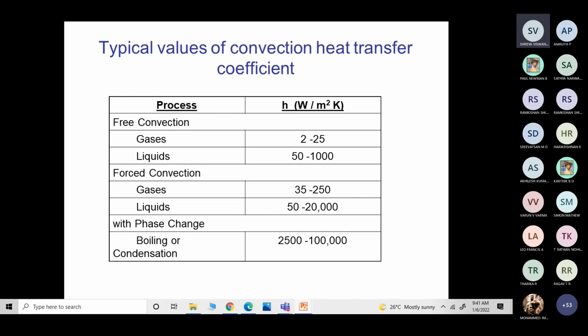See, again take the example of coffee. When you want to cool it, all of a sudden you transfer the coffee from one tumbler to another tumbler. That's why the vendor usually does that, right? He transfers fluid from one tumbler to another. So if bulk motion is important, transferring fluid from one vessel to another at a faster rate, automatically the Reynolds number increases, right? You impart a velocity; the greater the velocity, the greater the heat transfer. So in case of forced convection, naturally the heat transfer value is higher.